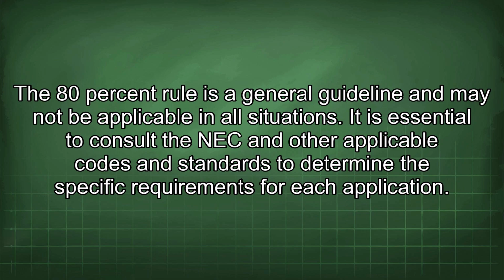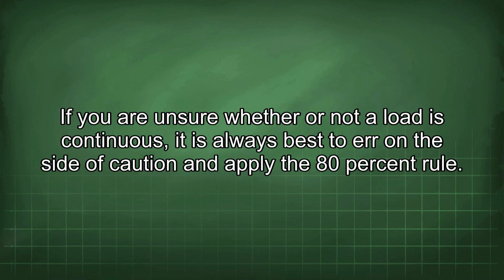The 80% rule is a general guideline and may not be applicable in all situations. It is essential to consult the NEC and other applicable codes and standards to determine the specific requirements for each application. If you are unsure whether or not a load is continuous, it is always best to err on the side of caution and apply the 80% rule.